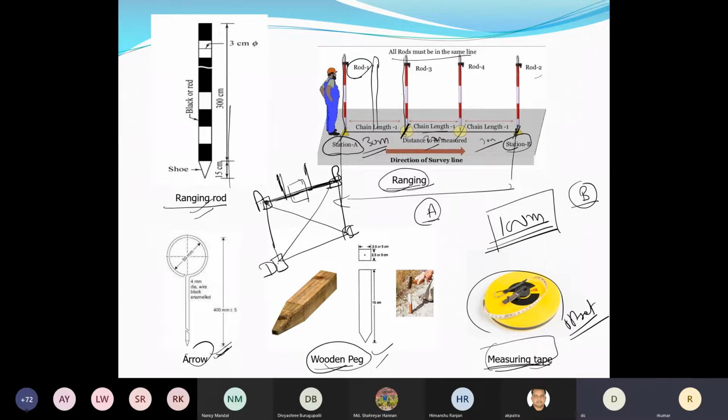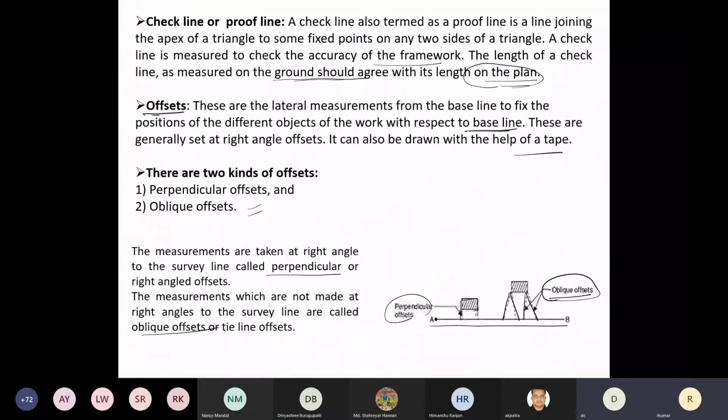The intermittent two are held by two more who are not on the line of sight between the first and the last. Those two intermittent locations need to be adjusted so that they fall on the line joining the extreme points. So that's the ranging operation. Is it clear? Yes, sir. This operation is known as ranging.